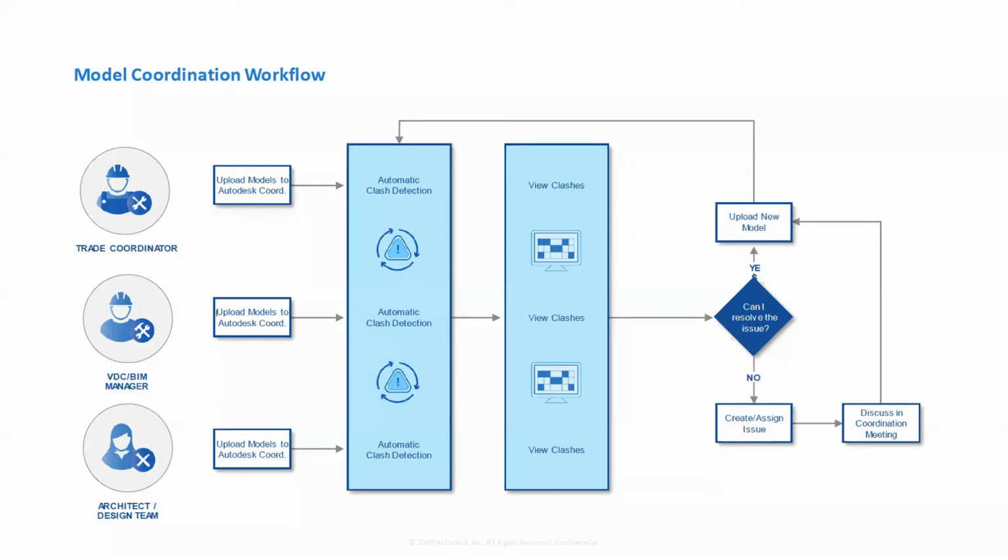It's through the 2D documentation side of things, but also now through BIM Collaborate, you've got this 3D model coordination side of things as well. So that can then be reviewed. So clashes can be reviewed. You can save images of those areas to highlight, and they can be marked up, and then issues created and assigned to users for them to be actioned, basically. And all of that history is tracked through there.